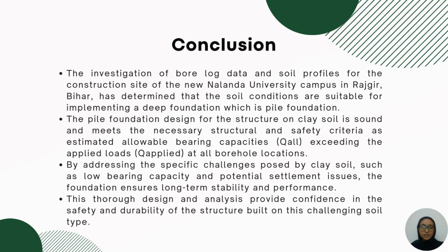Lastly, the pile foundation design for the structure on clay soil is sound and meets the necessary structural and safety criteria, as the estimated allowable bearing capacity Q allowable exceeds the applied loads Q applied at all borehole locations. By addressing the specific challenges posed by the clay soil, such as low bearing capacity and potential settlement issues, the foundation ensures long-term stability and performance. This thorough design and analysis provide confidence in the safety and durability of the structure built on this challenging soil type.